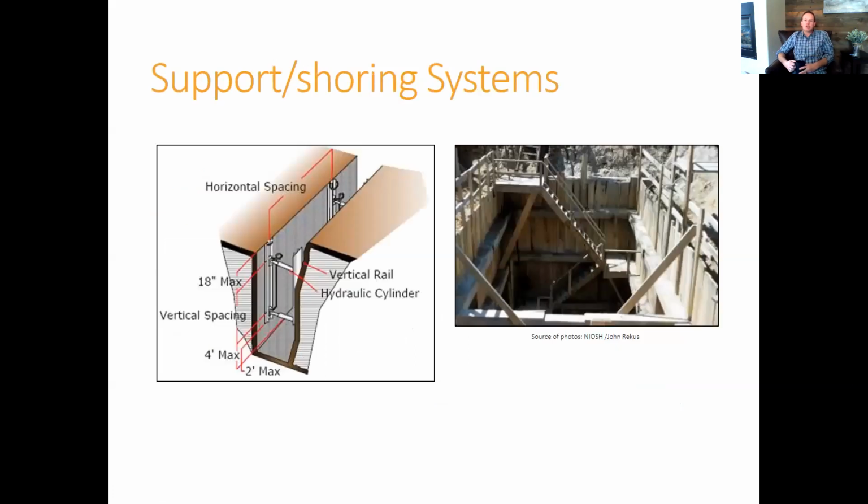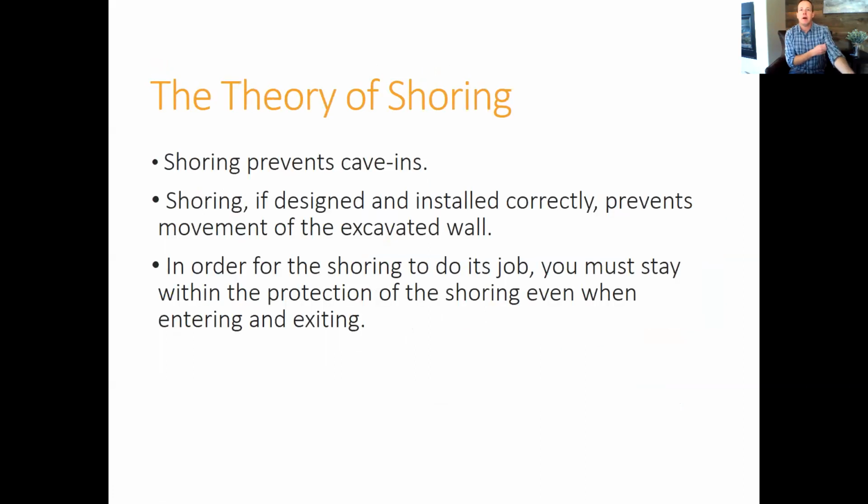Okay, so the support and shoring systems. Now, the way that these work is by pushing against the soil. Now, the theory of shoring, it prevents the cave-in. It's designed to push against the soil on either side and prevents the cave-in. Okay, and that's how it protects, is by preventing the cave-in.